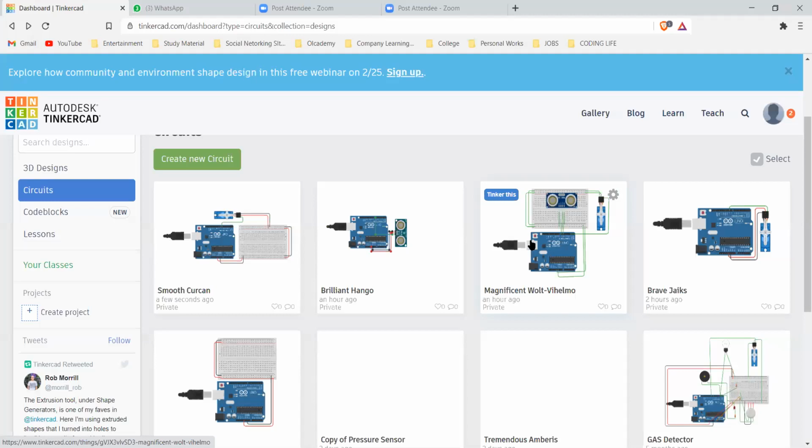With a gas sensor you can do multiple projects like CO2 detection in mines, harmful gas detection in households, or methane detection. There are various gas sensors. The most commonly used gas sensor is the MQ2. This gas sensor can detect smoke. It can detect fires. If you combine the smoke sensor or gas sensor with a temperature sensor, you can make a fire detection system. If you want to just detect harmful gases, then just code it, give it a certain threshold value. After the threshold value, it will give you an output.